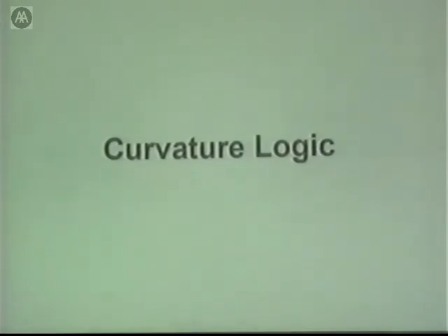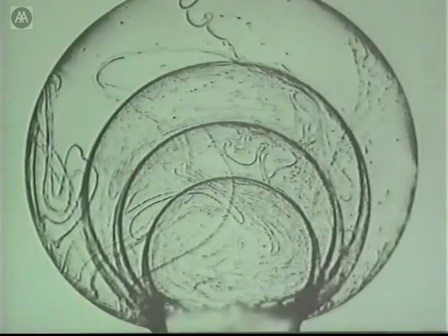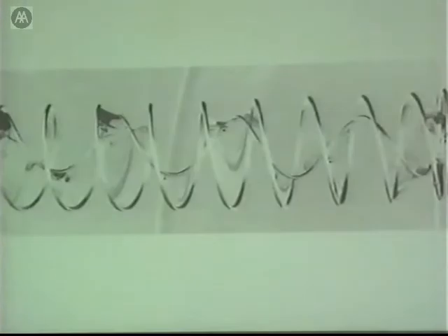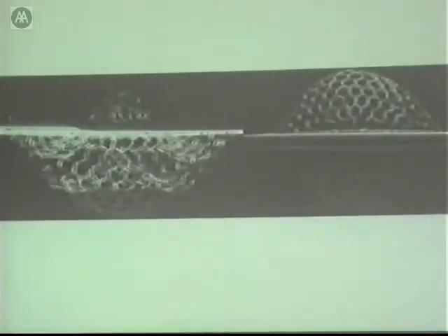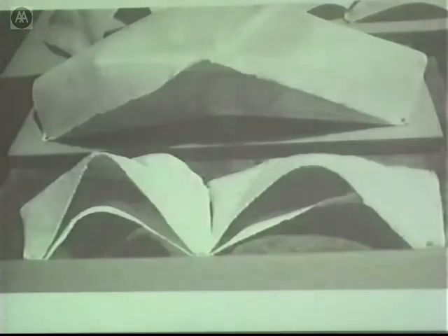So among those form-finding processes that lead to curved geometries, we have obviously the minimal surfaces, soap bubbles without any controlling edges, external controlled edges for soap film experiments. Obviously, we have the tensile stress suspended form, with linear elements, catenaries, and with flat elements, the suspended nets. We have, of course, the compression stressed inverted forms with flat elements like the grid shells, or with other flat elements such as the thrust surfaces as more continuous elements.